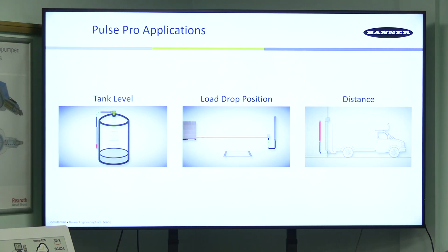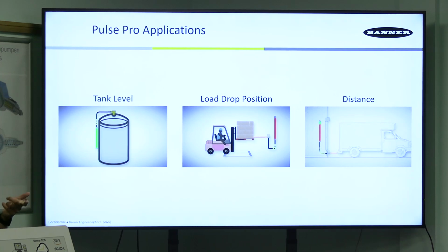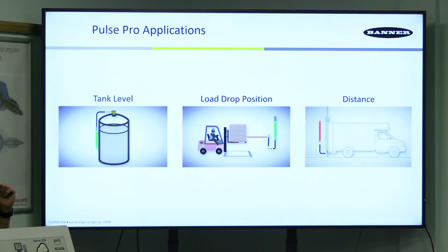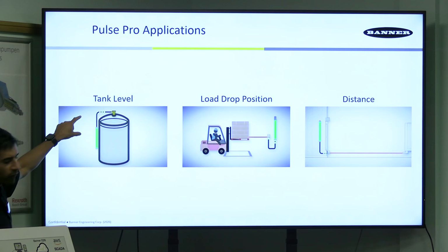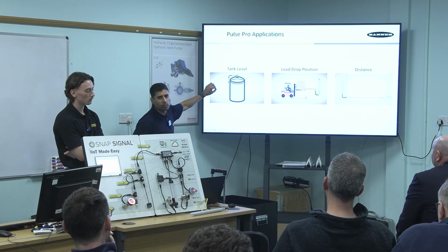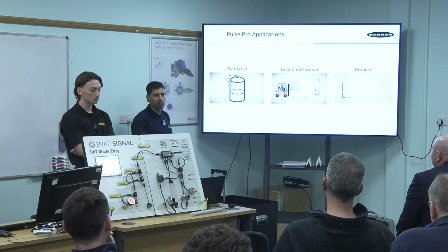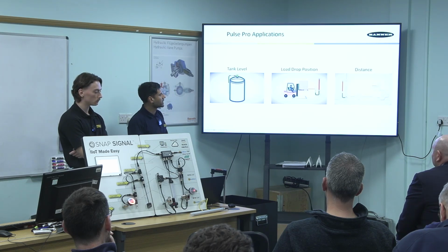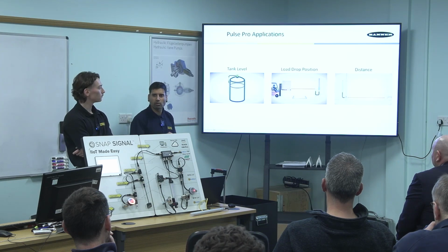And you don't necessarily need a PLC either. A lot of our sensors, our radar and our ultrasonic, have a pulse output, and our Pro lights, like I said, have a pulse input. So you can simply connect a sensor using one of our splitters. You just add power to it, and you can pretty much scale a light based on 4 to 20 milliamps. And again, the light is programmable, so you can set your different scales within the light.